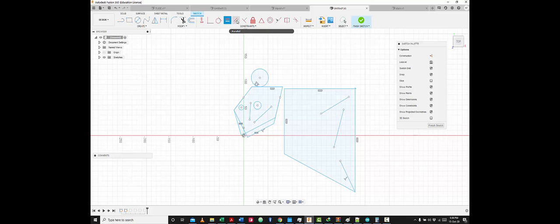Now the next thing here is the parallel constraint. So if you click on the parallel constraint, you can use it to make these two lines become parallel to each other. The next one I'll talk about is the perpendicular constraint. So I can click on the perpendicular constraint, click on this side and that line, and they automatically become perpendicular to each other. Now, the fix and then unfix is used to lock some geometric shape where they are so that no constraint can be able to modify them.